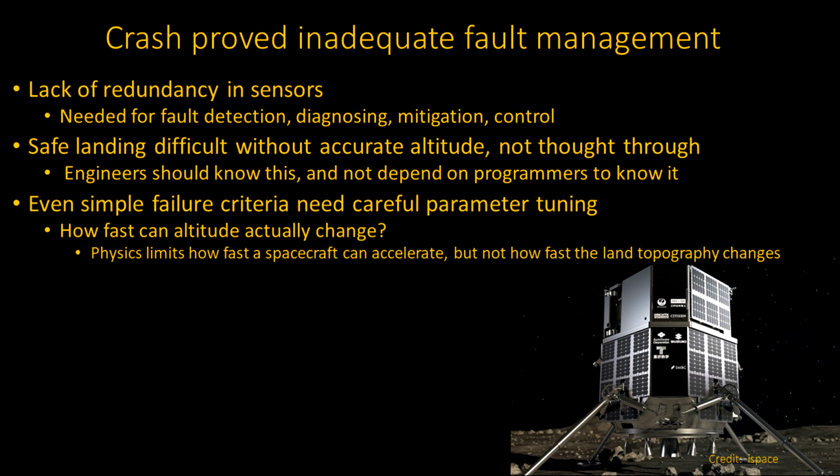First, the design failed. There wasn't enough redundancy in the sensors, or even a substitute using topographical information from camera observation. As a result, they failed in fault detection and diagnosis. They concluded that the altimeter was bad when in fact it was correct. They also failed, especially in not designing fault detection and diagnosis for cases they would encounter, which included landing or even encountering a crater.